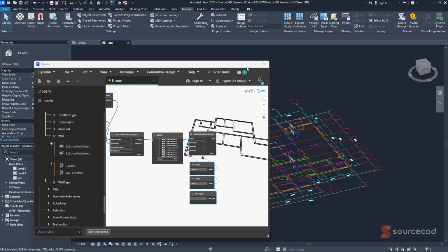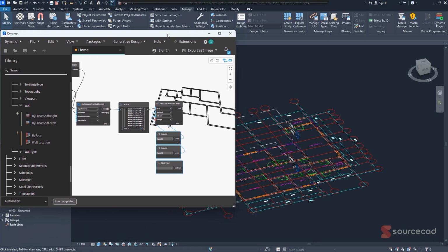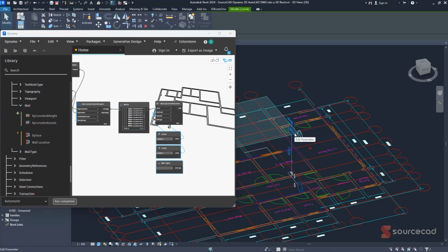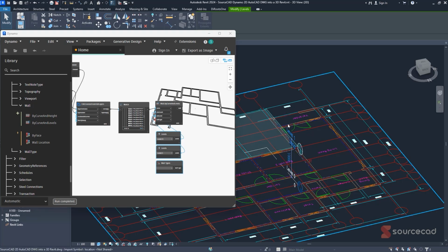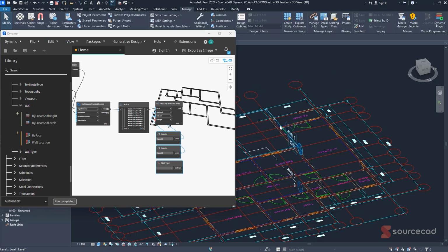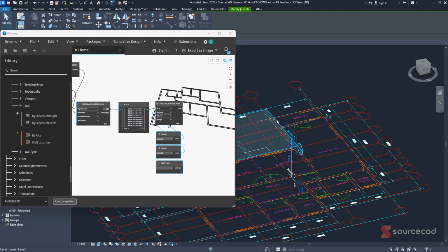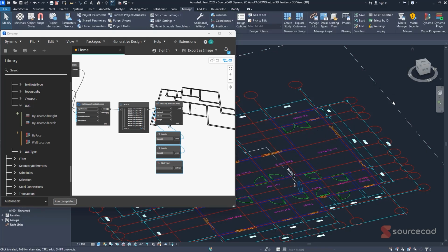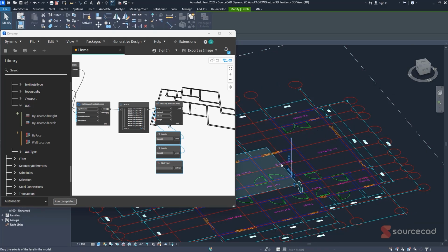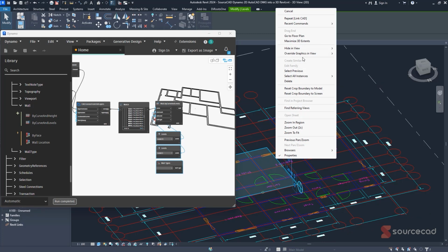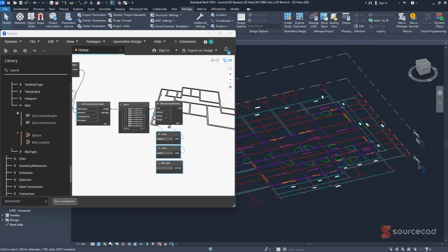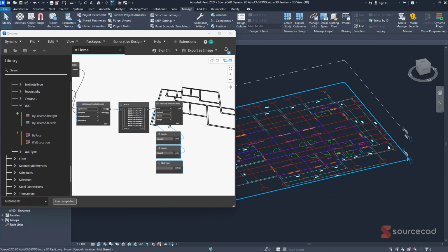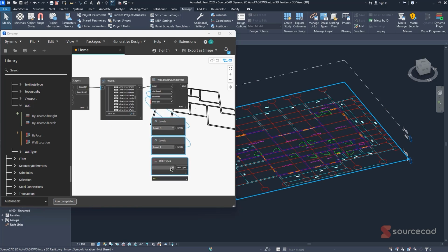And back in Revit, so we still have Revit here. I can click on 3D so that we try to see what's happening in real time as we are working on this. The level that we have here is 4 meters. So let's just update this to 3 meters just to make sure that everything is still to standard. Right click, then go to maximize the 3D extents. The same with this, just right click and then maximize the 3D extents. So those I'm just doing to fine tune what we have here. It's not linked to this. So now let's finish it up.